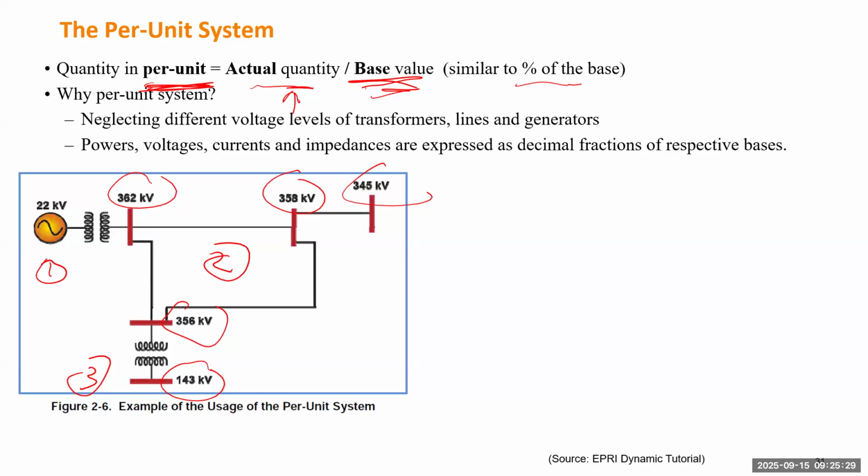Okay, so if we divide each number by their nominal value, rated value, or base value, we will get the percentage of voltage everywhere. If the system is operating completely in normal condition, everywhere the voltage should be around 100%. Otherwise, there will be some violation and reliability issue. So we just choose 20 kV, for instance, 345 and 130 kV as the base voltages. We just assume those 3 numbers are their nominal voltages.